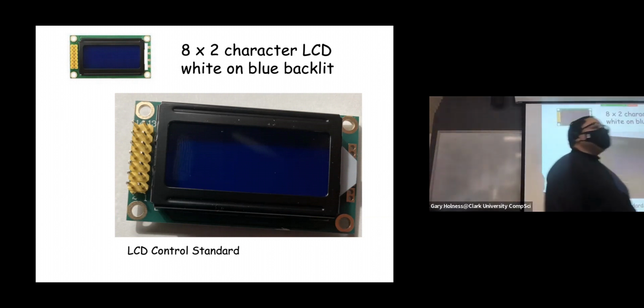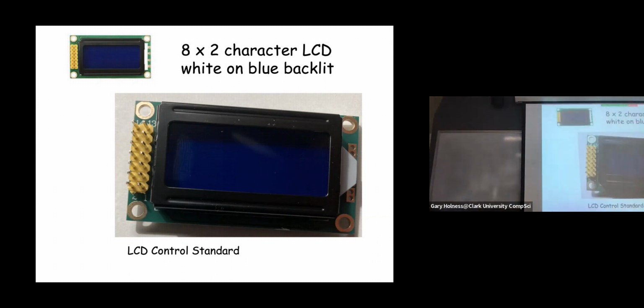Now, these pins include a data line, a data bus. And so the more real estate you have on the LCD screen, the more addresses for locating where things are going to go, the more complex the logic, and you pay for that with a higher cost. In addition, the data bus is bigger. In addition, from a form factor standpoint, if you have a larger screen, that's more liquid crystals you have to energize to light up, and that's also going to sink more power.